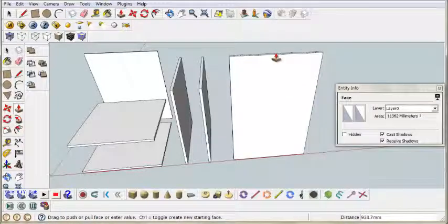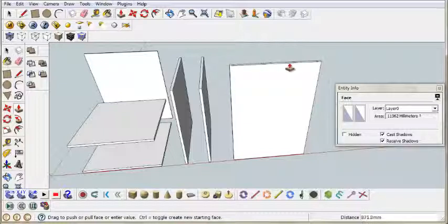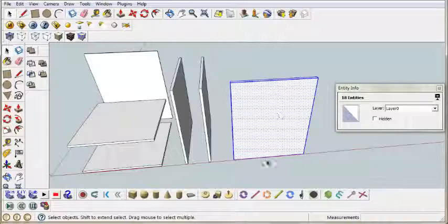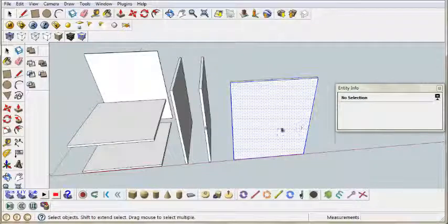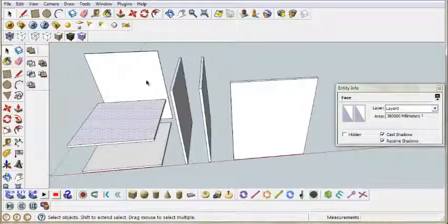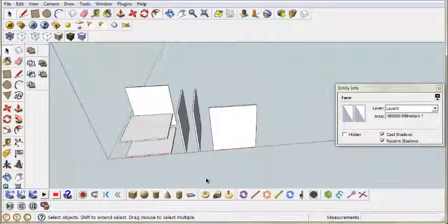and then here 750. So let's subtract at least 4 mil so that we have a gap of 2 mil on top and the bottom, or maybe let's just subtract 2, so 1 mil each, so that we are a bit uniform. Let's make it 548. Now you have your front door, the left and right panels, your bottom, your top, and your back. That's a lot easier, right?